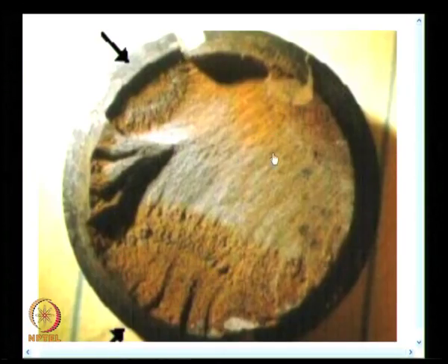This has a different texture and this has a different texture, and you could guess that this is the growth phase of the crack, and this crack has grown bigger than this. So, eventually this would have precipitated the failure. This is one aspect of this. You can have multiple cracks, one of them may be critical.